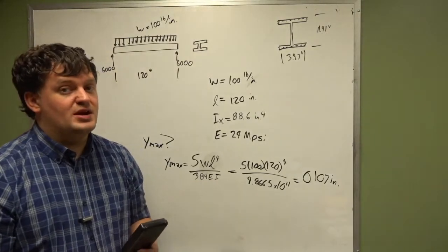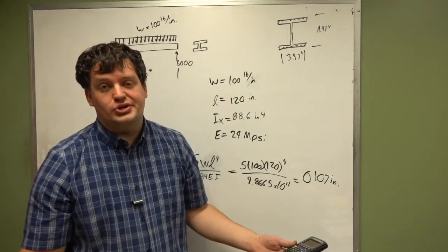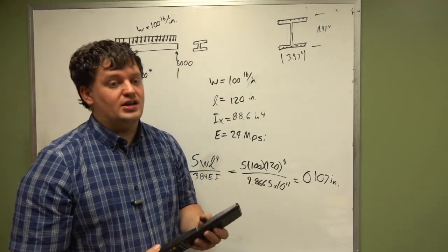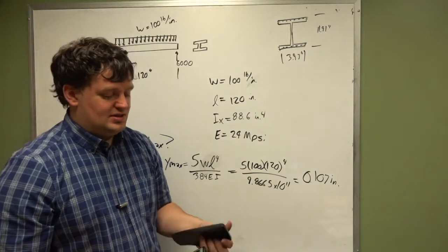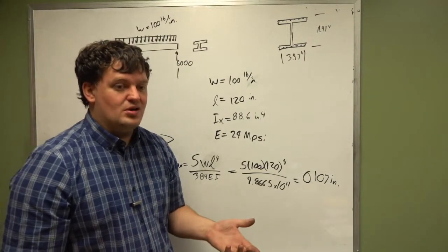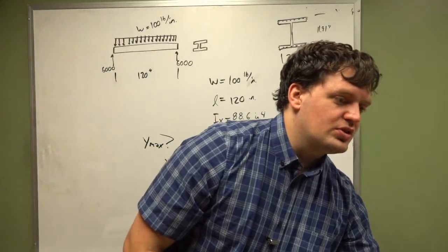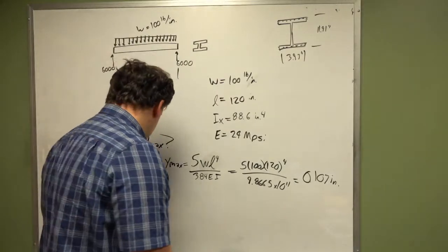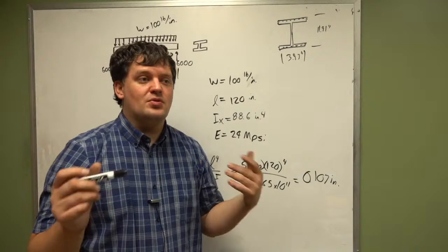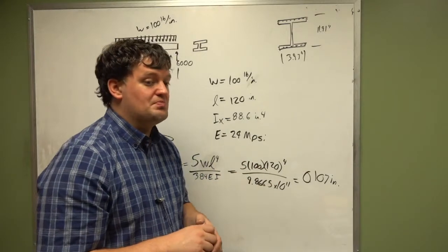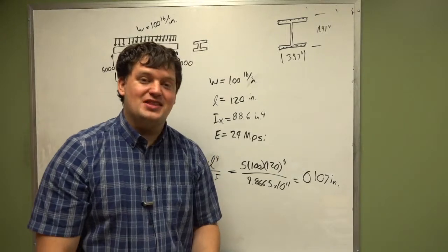Usually you will get deformations that are even less than 0.1 inch. You should. If you're getting massive deformations out of your system, and your system is only a foot long, you're doing something wrong. And that's really the issue with deriving a lot of these equations. It's not hard to do an integral. It's hard to remember to carry the numbers so that you don't end up suddenly getting something ridiculous. When I was in college, that happened to me a lot.